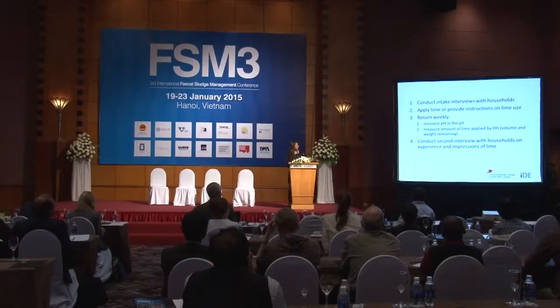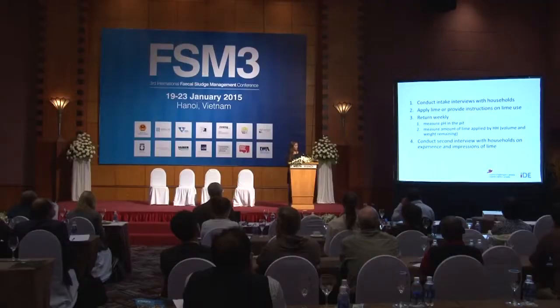It's in 2 different districts, about 40 kilometers apart, with Phnom Penh in the middle. These are quite rural areas. So initially we conducted interviews with the households, then provided instructions on how to use the lime or applied the lime for them, and then returned weekly to measure the pH in the pit to see how well this was working. We also measured the amount of lime left in these buckets to see how well the users were actually following our instructions.